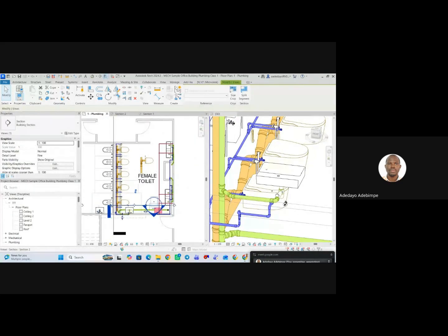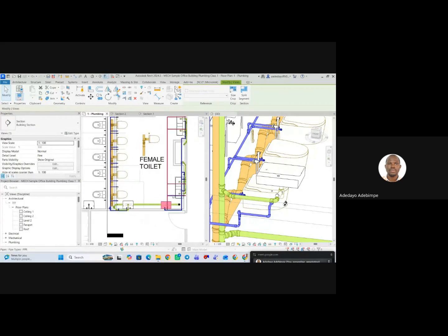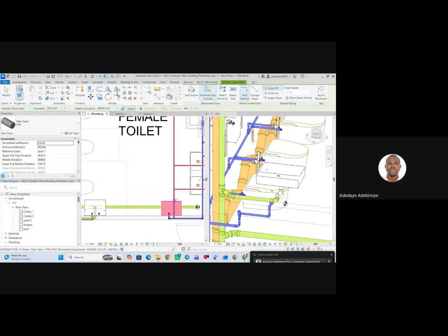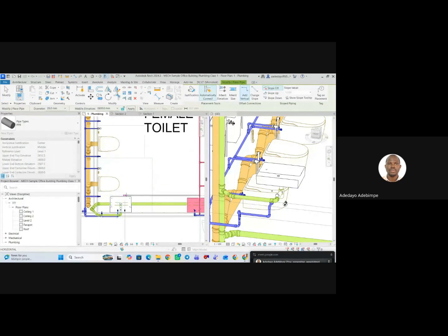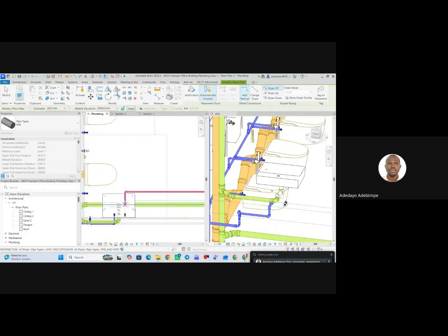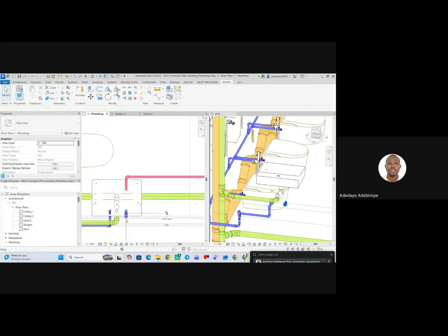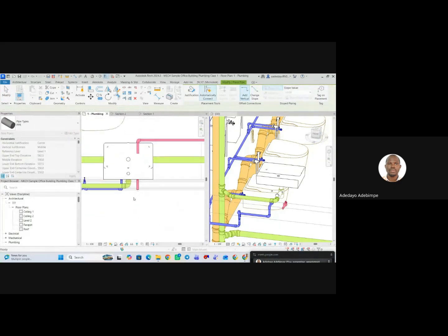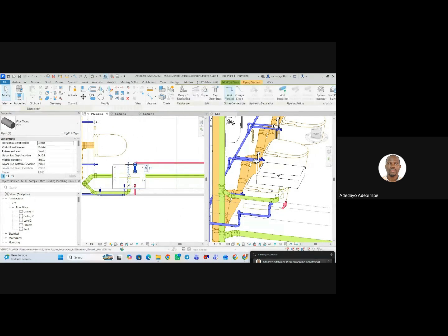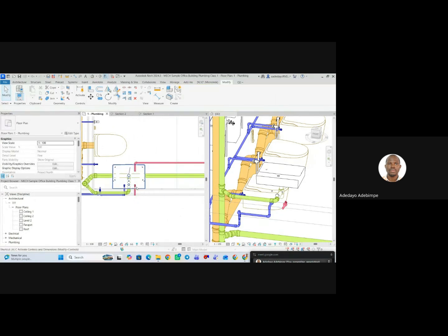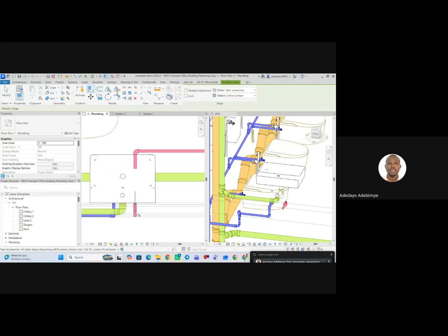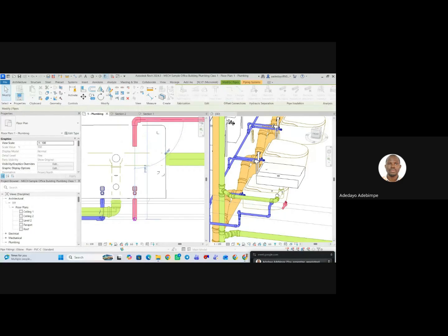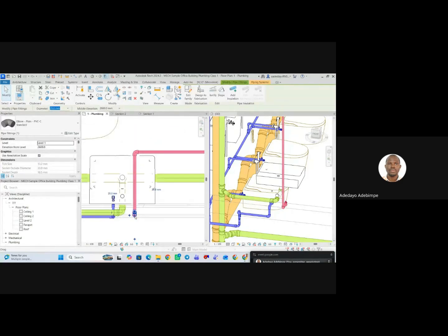So to connect our hot water, let me create a similar one and drop it here. Then draw a section of pipe out of my hot water pipe. Then connect this into it. So I need to align first. AL, align. So we have that.